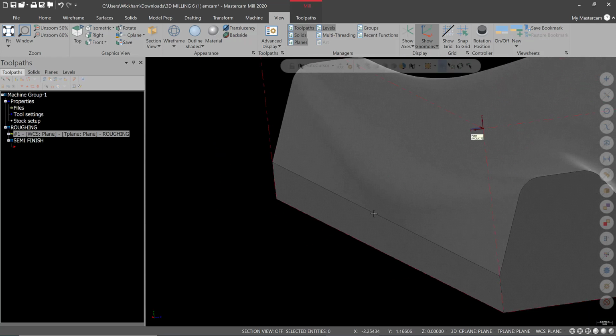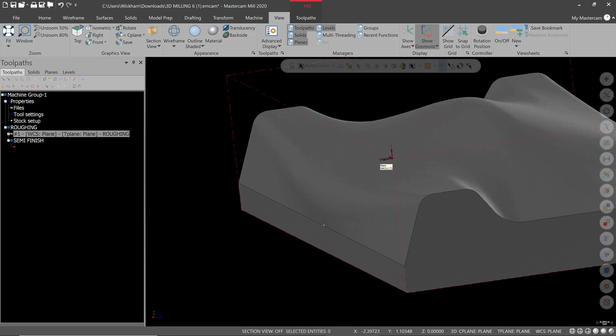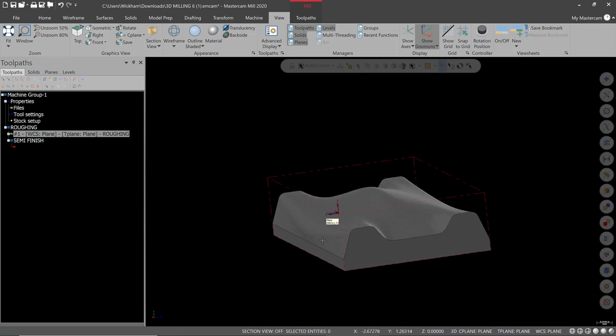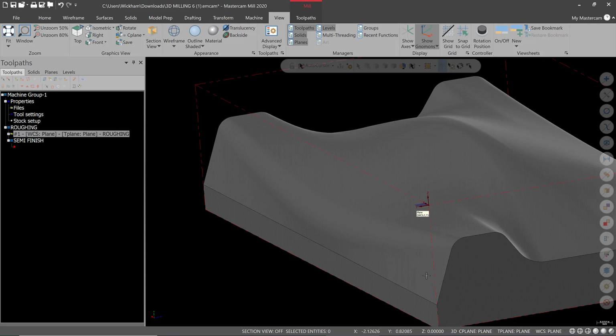So unless we add material here, or you can also extend this out a little bit, it's going to dance over this because technically there's nothing right in the center here. This is a flush surface, and that's what really exists. So I'm not going to really worry about it for this because we are just starting out here. This is very easy to blend at the machine. It all depends on what kind of tolerance you would have to hold here, if you need a straight pass here.